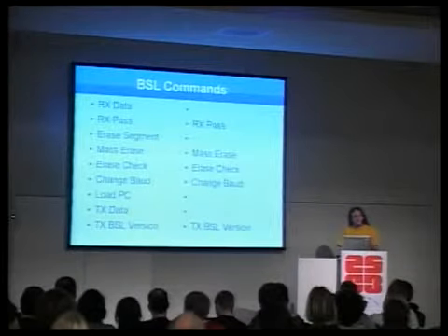Also worth mentioning is that the change baud rate command doesn't actually change the baud rate. It actually changes the clock rate. We'll get into how it figures out serial timing, but in some versions you can change the baud rate to something very high, actually setting the clock very high, and then you can brute force passwords faster. Conveniently, those are the ones that my timing attack does not work against.